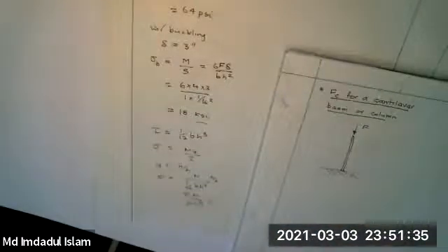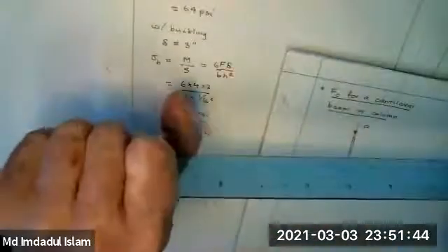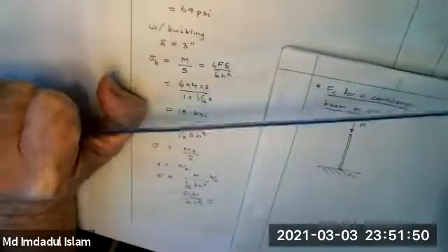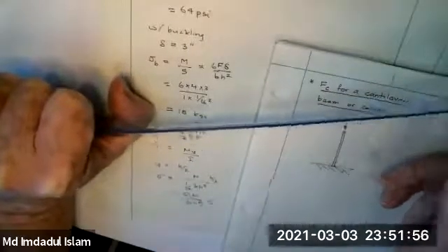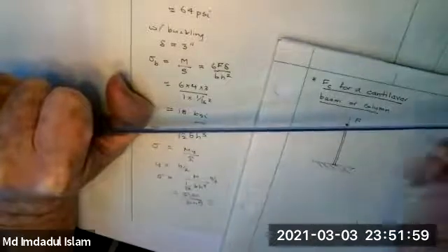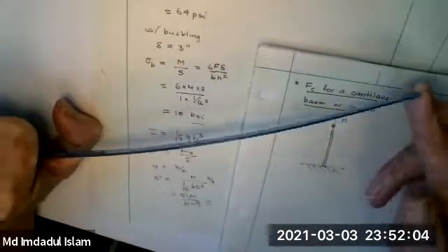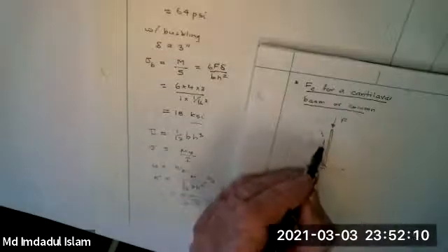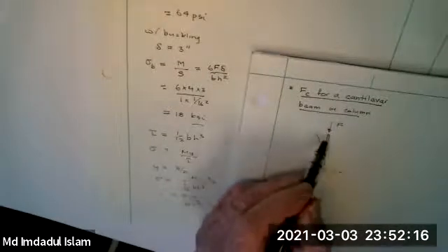And if I do something like this, if I build it in, so I'm holding it here, okay, and so it can't rotate at the end there. It'll go like this. I may be providing a slight lateral load there, but I'm trying primarily to provide a vertical load with the fingers. So it bends like that. And it's perhaps not obvious whether this is going to be easier to buckle or harder. This support stops rotation, but I have no support on this end.